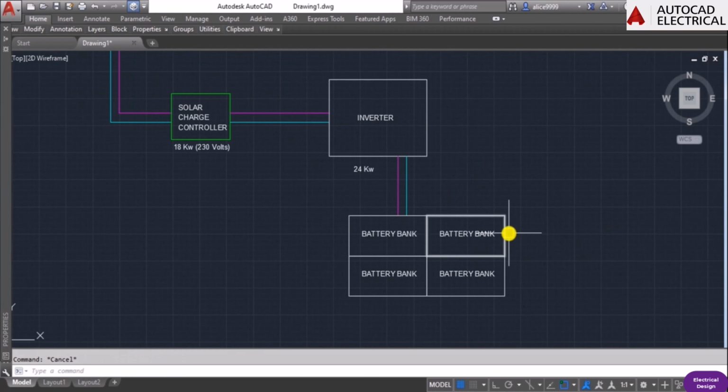A battery bank is something like this. There are multiple racks available in the battery bank, so in the multiple racks we can store the batteries accordingly. So this is the battery bank. The inverter saves the power into the battery bank, and then we can use the battery as per our requirement. Battery capacity is calculated as per the total demand required per day.